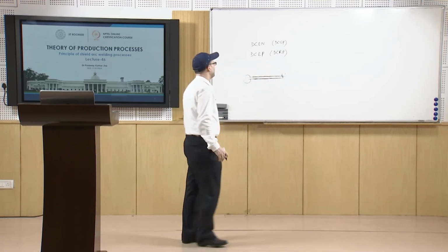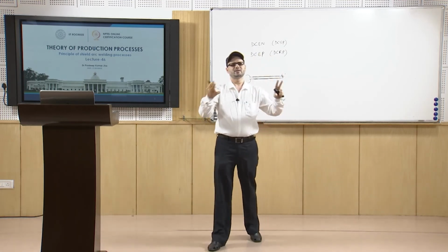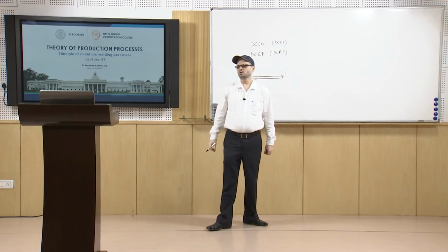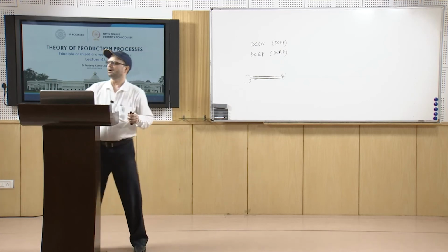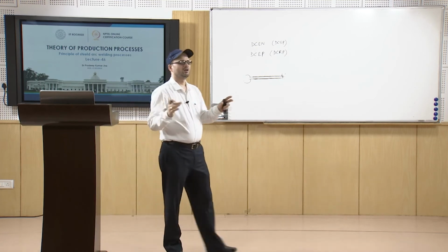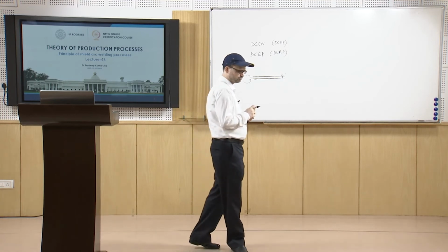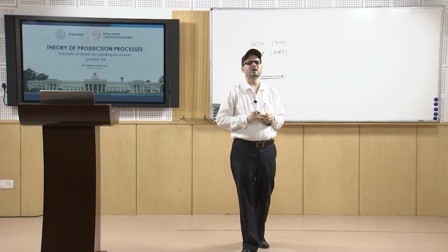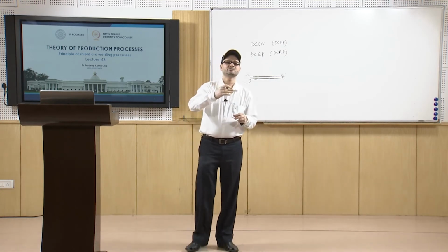Second is that once the flux is melted, it creates an envelope of gases around the weld pool. In that case, it protects the weld pool from any atmospheric contamination, as long as this coating is getting consumed, and as you are moving for welding, you have the envelope of shielding gas generated.